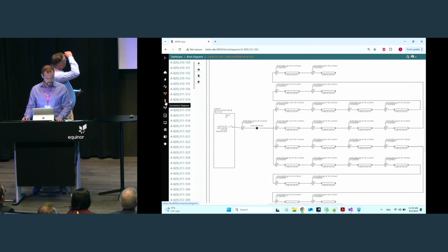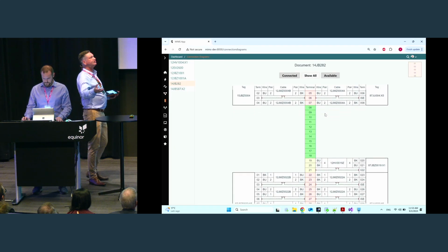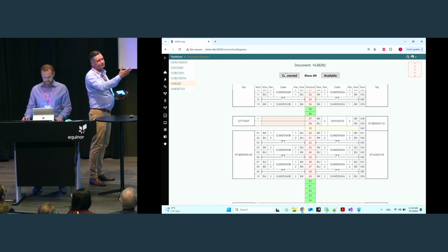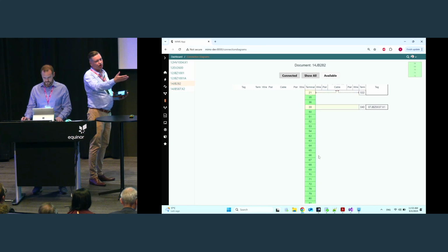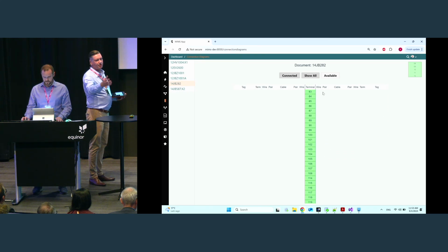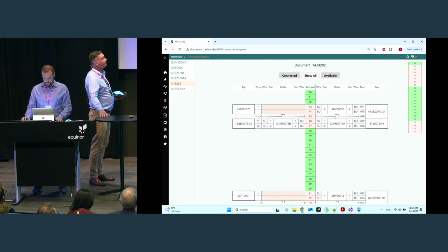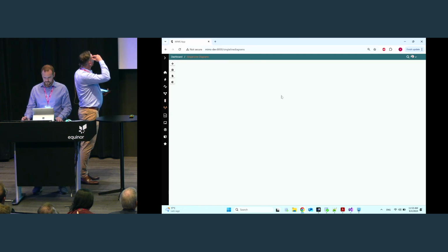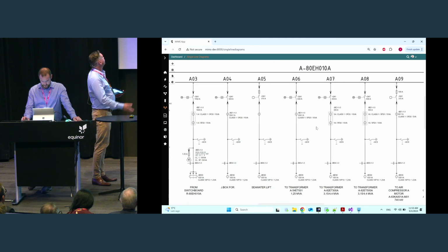There was also a request for connection diagrams, but we saw that using them as a diagram would not be so efficient. So we define just a view, so we can see every terminal strip and what is connected to every terminal, and find available terminals to possibly find the shortest path to the control system if you want to hook up a new symbol, for instance, in a brownfield scenario where I want to make a modification. We also did a single line. Again, this one is also streamed straight from the database. And yeah, it's what it is.